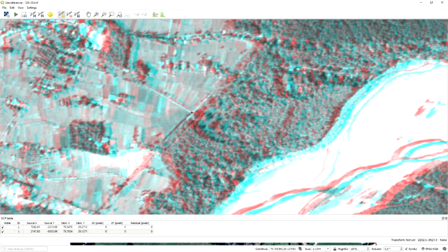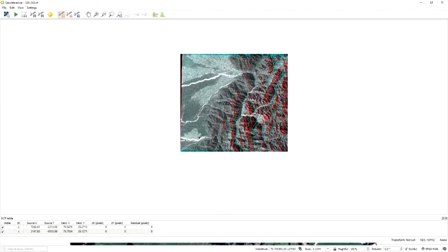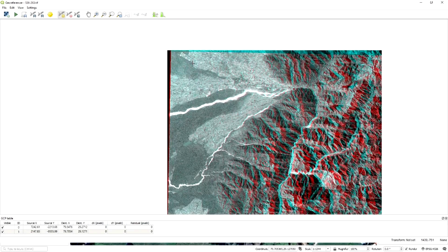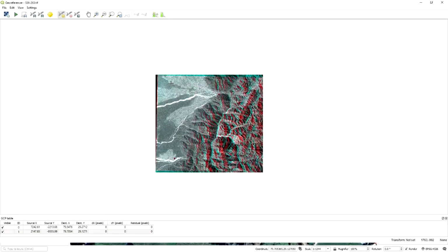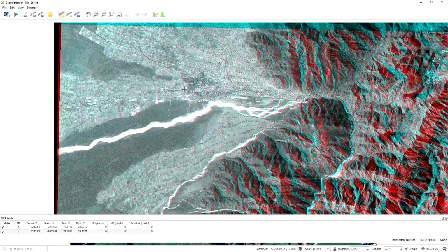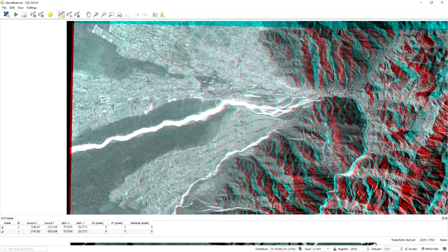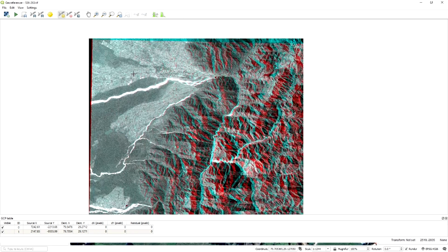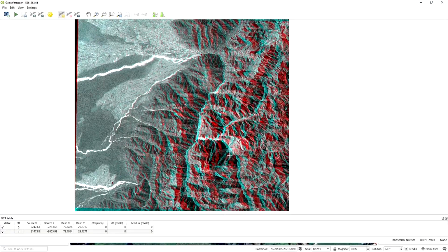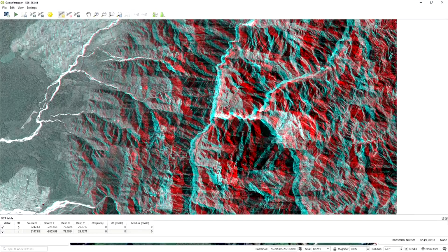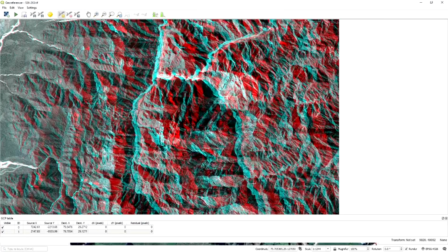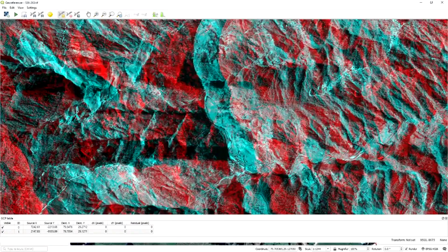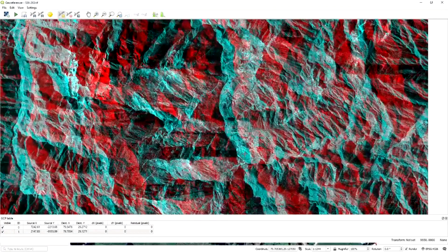If you are clustering your points at a particular place or location, that would ultimately create some kind of error with your georeferenced map. The best way is that you can choose 4 points from the 4 corners of your map, and if you add some more points, you can choose points from the center portion of your map.